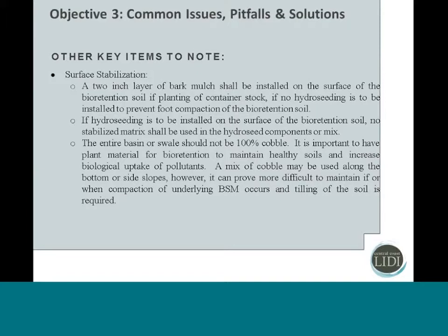And then the bottom bullet here, this was a lesson learned from one of our projects. The landscape architect had basically covered the entire bioretention facility with cobble. There were still plants dispersed throughout, but it was pretty much all cobble. And this was one of the projects that had a compaction issue.